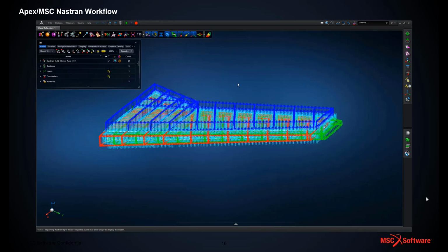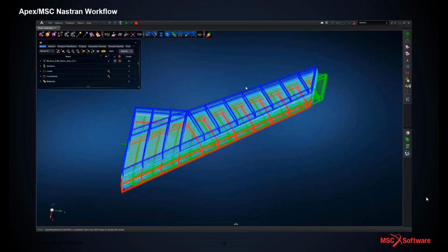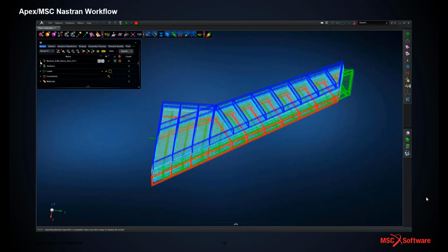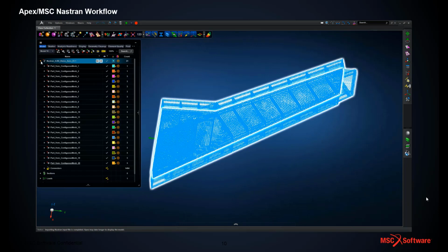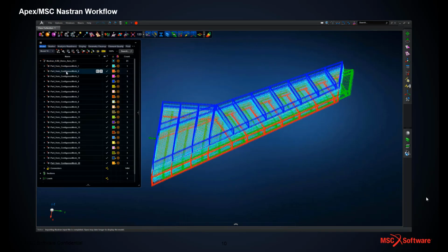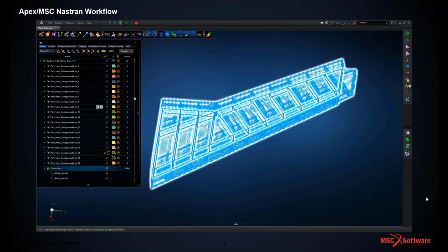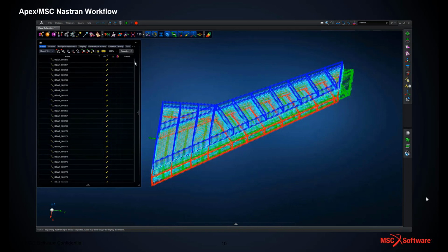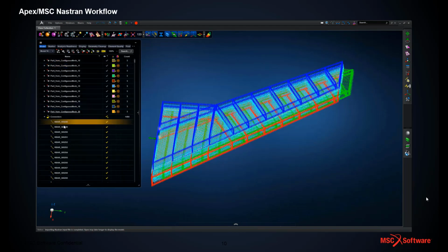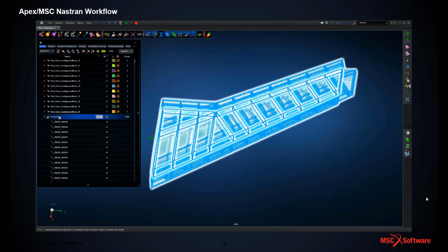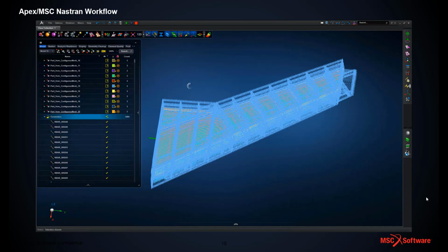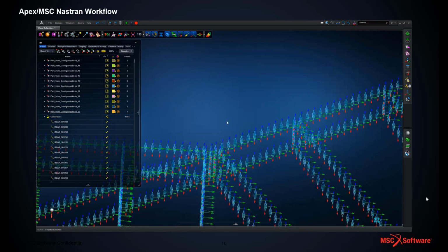Simply import the model and in comes the model, and we can see in the model browser tree on the left hand side how the model has been effectively generated or archived, if you like, to respect those individual contiguous mesh parts. We've got a number of connectors within the model, shown here, zero length RBARs for this type of model. We can look at those explicitly.